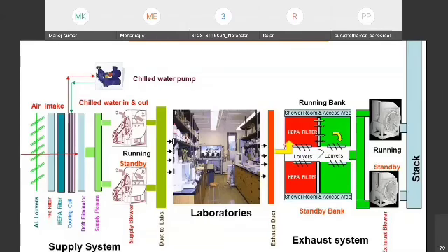And this air will be released through this. We'll have two systems, one running and one standby. In case one is getting choked, we'll have dampers. We'll close this, and air will pass through the other, again under systems operation. This is called the once-through ventilation system.